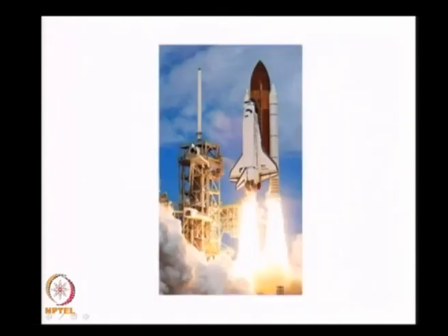At the bottom on the right hand side, the opening opens out, some flame comes out, and when this flame comes out, it hits against one of the attachments which is attaching this to the main rocket, and that gives way, and this fellow comes out and gives a thrust in some other direction. Not only that, this flame hits against the hydrogen tank which is available in between, and spills the hydrogen. This happens at a height of around 14 kilometers, and well, what could happen? There is a huge fireball and the entire mission is a failure.